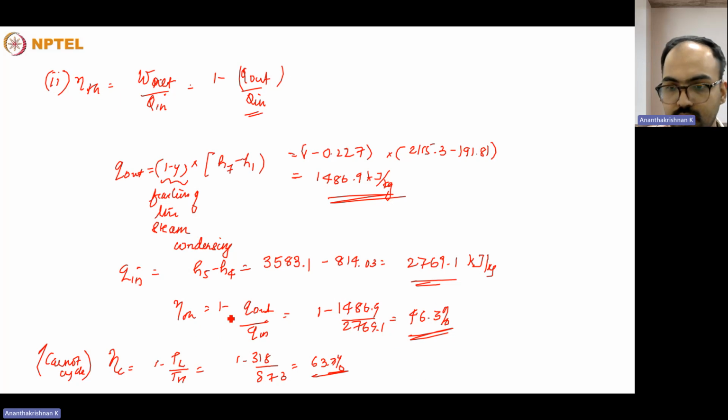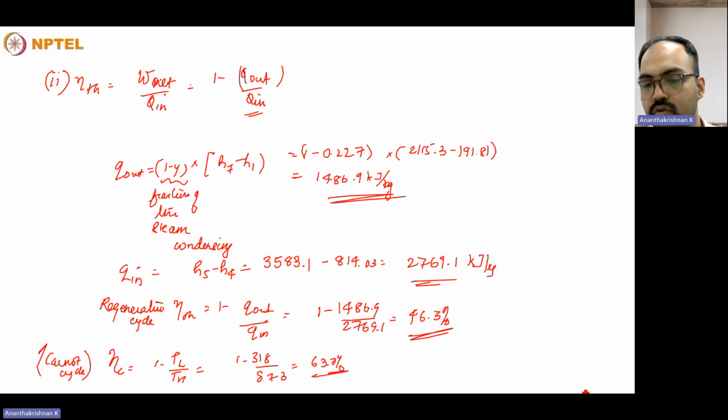And we using these kind of slight tweaking to the model, just like the regenerative cycle, we are trying to improve the total efficiency to reach the same 63%. It's not possible because irreversibilities are involved in the case of these type of cycles. That is, in Carnot cycle, it's a completely reversible cycle, so we ignore all the irreversibility parts. So that is a theoretical possible maximum. But we are actually trying to maximize the efficiency that we get through these kind of small tweaks.